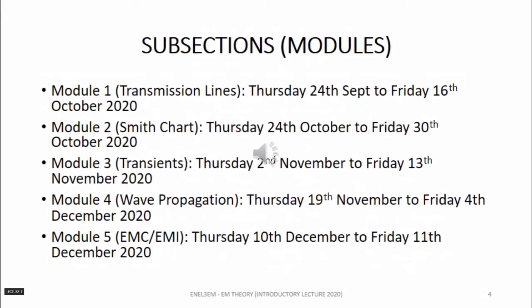Now, for about 3 weeks in November up to early December, we'll be looking at wave propagation, and we will start with Maxwell's equations, and from Maxwell's equations we'll end up with our partial differential equations, which we will then solve for waves in unbounded media, which means waves in free space, and whatever the medium, it is unbounded, and from there we'll get the intrinsic impedance of the wave, and then we will also get the attenuation and phase constants.